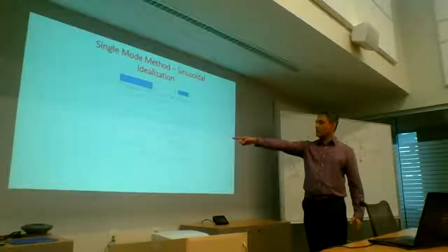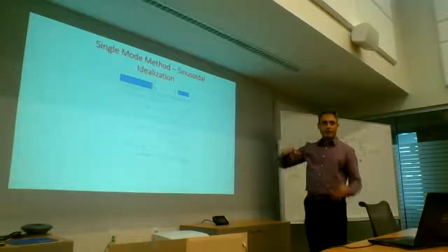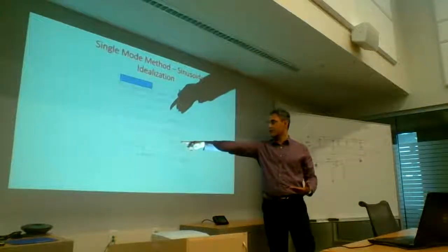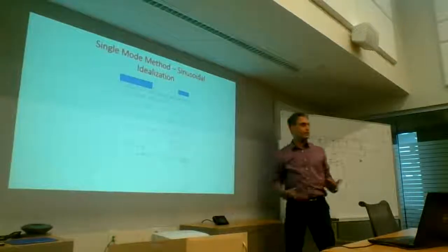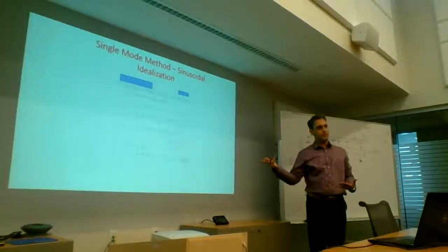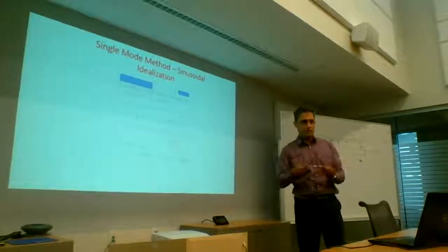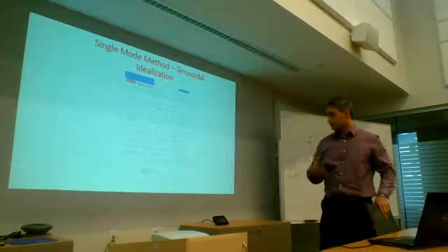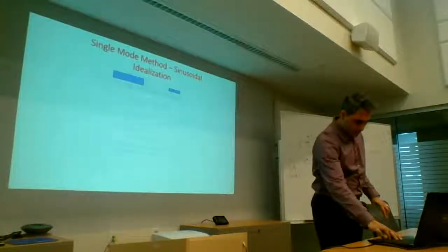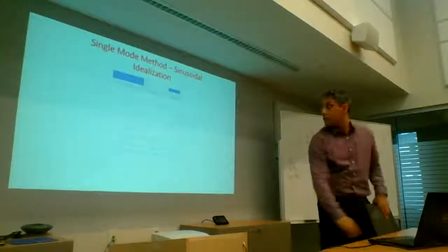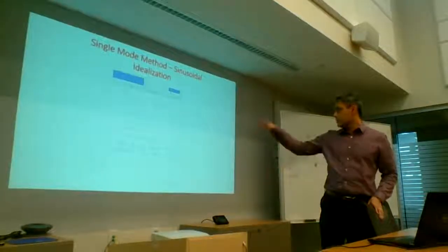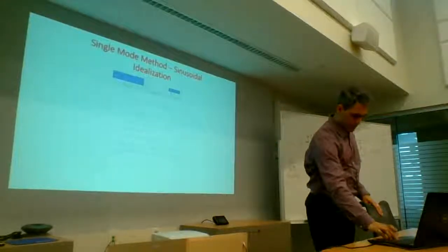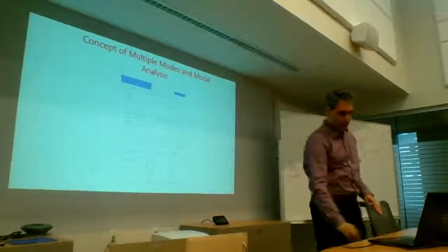And my effective load, the maximum loading intensity, because it's changing, so I just compared the maximum. I got about 134 kilonewtons per meter versus 137 kilonewtons per meter, which is based on the code methodology. So again, you can see that there is a fairly good match there. Okay, so this just goes on to talk about how that sinusoidal idealization was prepared, or how we came up with that.